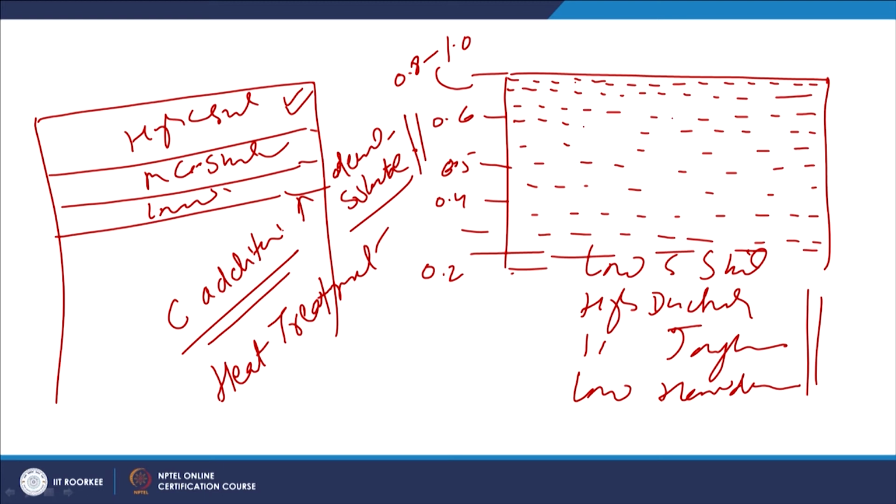Accordingly we will be able to see the martensitic transformation. Since the carbon content is more, on the austenite to martensite transformation we will get the higher hardness, highest hardness will be here in this top layer band, and thereafter there will be a second band where the carbon content is slightly less. Here we may have pearlite plus martensite, and martensite also of somewhat lower hardness. So, this zone will be slightly softer, and further softer zone will be there in the subsurface region.